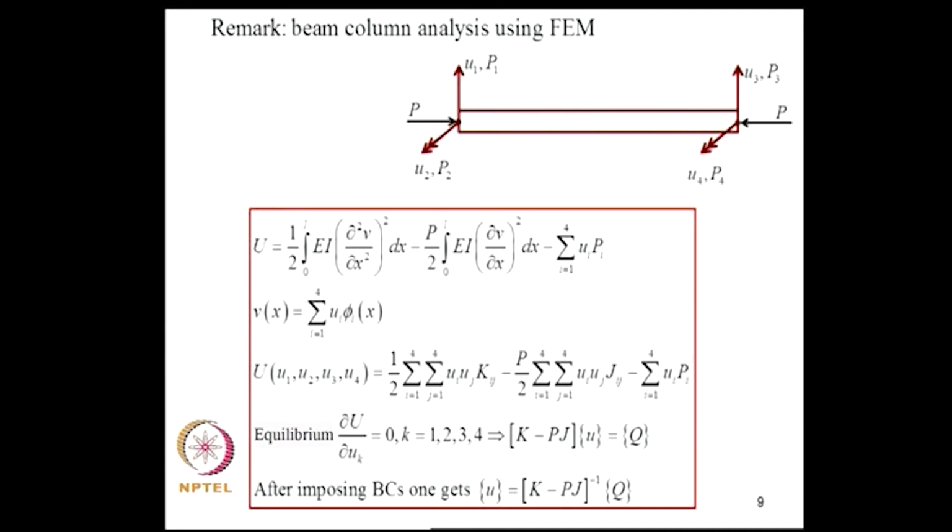Now, in the discussion so far we have discussed determining the load factor that helps us to determine the possible existence of a neighboring equilibrium state in the structure. But we could also do a response analysis by including geometric stiffness even when the structure is not on the verge of buckling. The loading may not have reached a critical state, but still I may like to include the effect of geometric stiffness in characterizing the response.